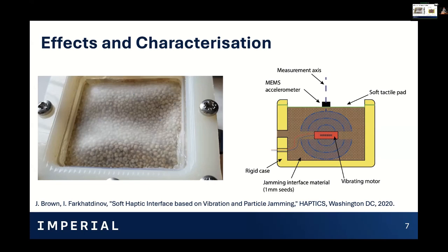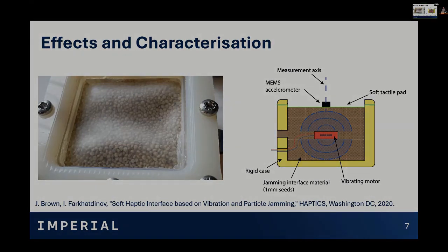Yeah, but it looks like the surface has a certain sinusoidal shape. The surface, that's not to do with the vibration. That's to do with the compression of the silicone causing it to expand. So the silicone patch there is actually slightly oversized because you compress it at the edges to seal the container. So why does it get pulled somewhere and then pushed the other way? I don't get it. So that's the air pressure change. When you inflate it, we were doing some inflation here as well to show the shape changing properties. So that's where it inflates. And then when you evacuate the air, it sucks back down. But it won't sit flat because, of course, it's slightly large.